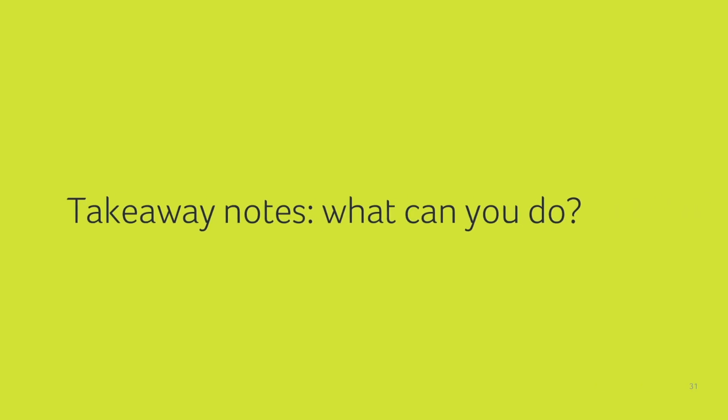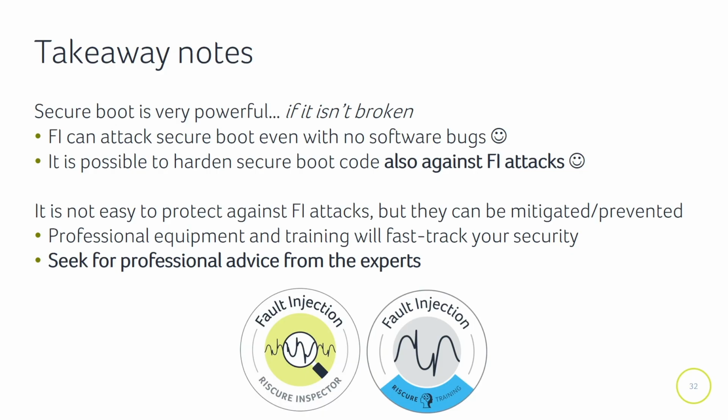Takeaway notes to summarize this short presentation. What can you do? Secure boot is very powerful. This is a beautiful design and it will help you a lot, but this will be true only if it isn't broken. If you're an attacker, fault injection can attack secure boot implementations even with no software bugs. Because in some cases, we will be creating our own bugs, like in this combined copy. We created our own buffer overflow.